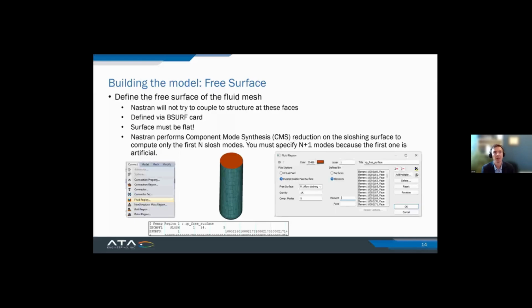Of course, it depends on where you're getting the trajectory file from, or how tightly your interaction is with the person who does that computation. Just make sure whenever you provide a fluid model, you tell the person that this is only valid for a specific acceleration value. And if they want to change that, then they only have to go into the incompressible fluid card and modify this value here.